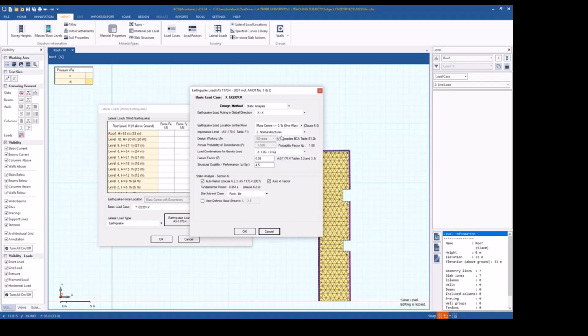In this case, you can actually apply the 30% here. So say 0.3G. You have to introduce another case. I know here we're going to have your 10 cases, but because of this 30%, we will be required to introduce another case that will allow for the 30%.